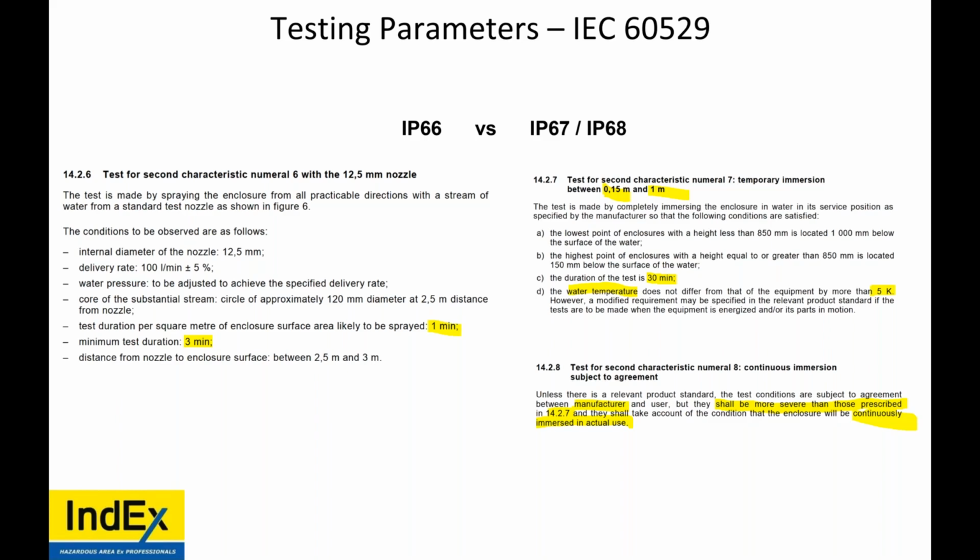To install a flame-proof enclosure into a classes and divisions location where explosion-proof equipment is used is highly dangerous. To install explosion-proof equipment into a classes and zones location, or zones, that requires a fitness for purpose assessment by the end user's responsible engineer, the responsible person, owner engineer, or somebody else has to make the call.